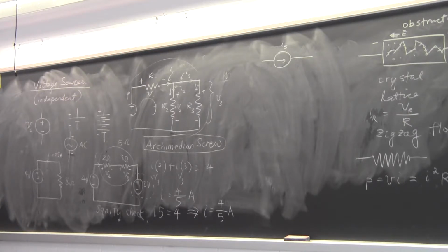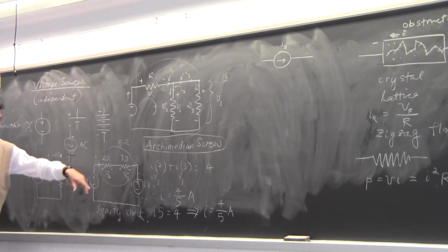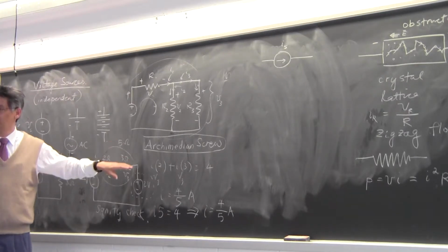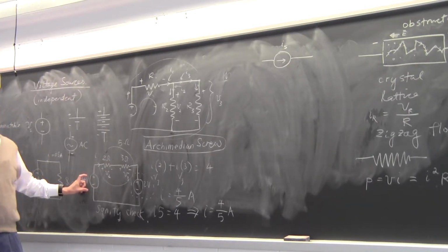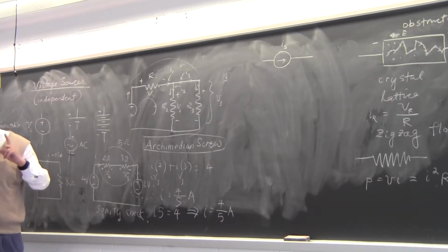And you can say that voltage sources have this property, that this value is immutable, or does not change. Okay, this value of the voltage source does not change irrespective of what you hook to this voltage source. You can add a resistor, you can add resistors of any ohmage. This value does not change. That is a property of an ideal voltage source. Of course, in real life, there's no such voltage source.